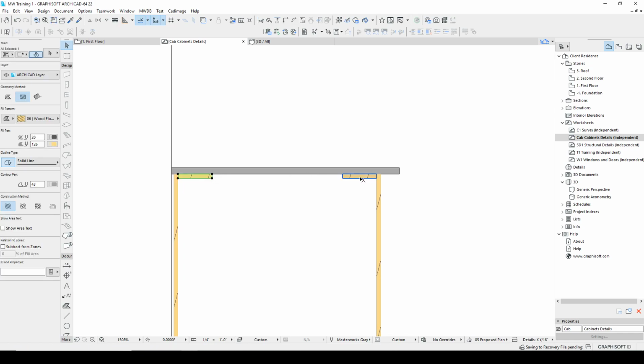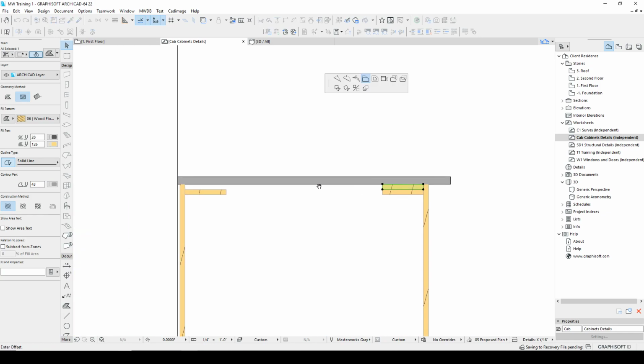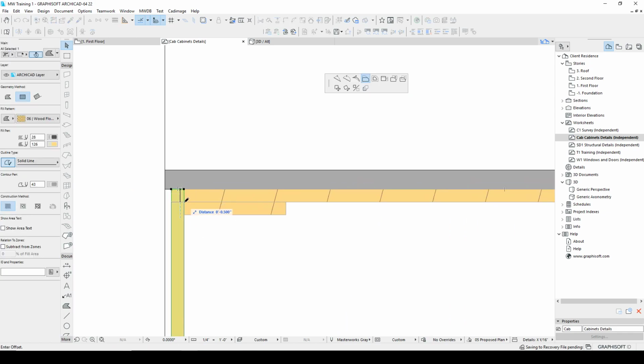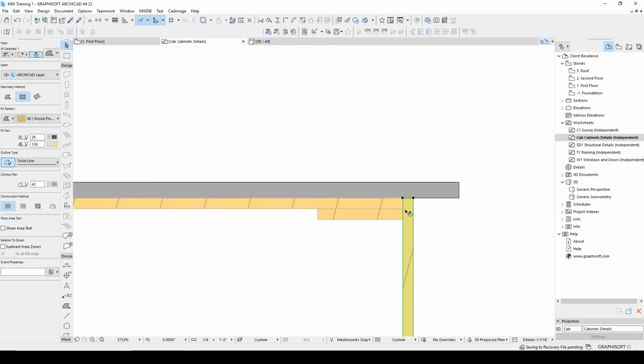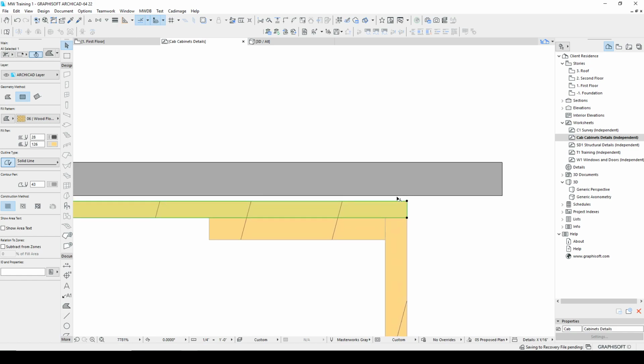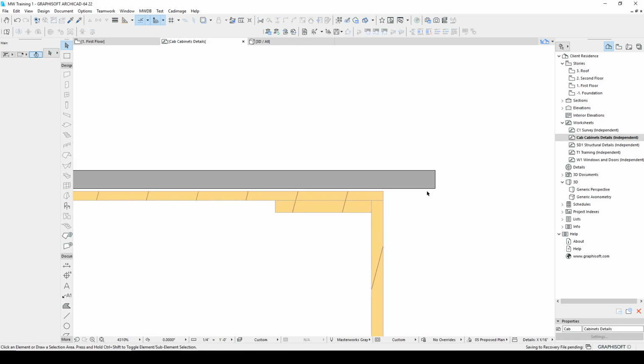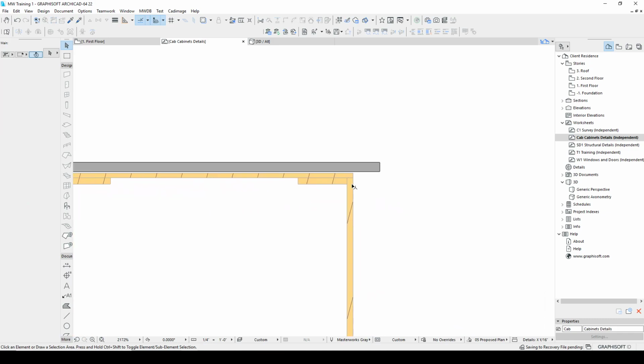Now I need a subtop on here, so I'm going to move these down 3/4 inch, copy this up with F9, and this will be my subtop, which means that this needs to come down so that you can see how nice it is to use fills, because I can just pull and tug and get everything to work just the way I want. And typically subtops are actually 5/8 with normally 1/8 of an inch of caulking or some adhesive to put the countertop on.